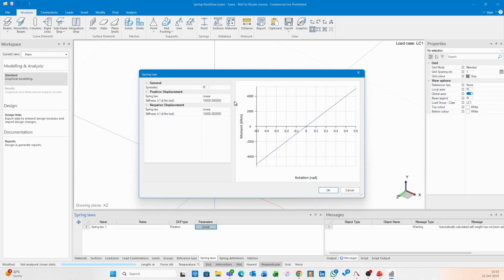Now, this can be as simple as a beam connected to a column with an end plate, but that end plate extends further down at the bottom of the beam than it does at the top. So, of course, that connection is not symmetrical about its x axis in that particular case. So it will have a different stiffness upwards than what it would downwards. In this case, we can adjust those values. So we can maybe set this to something like, let's say, 1,500. And for now, I'll keep it symmetrical. In our deep dive, we'll look at this in a bit more detail.